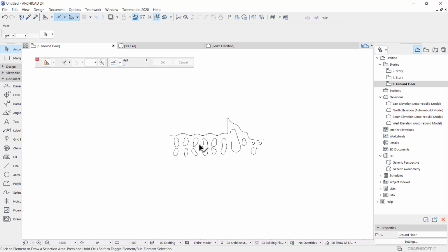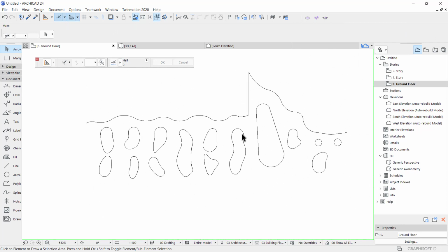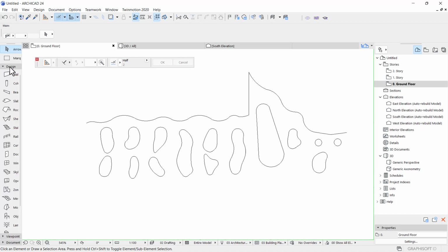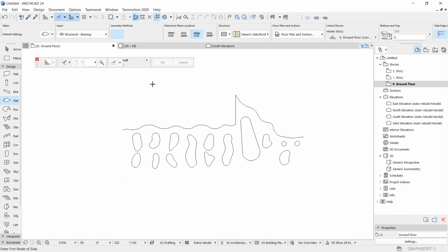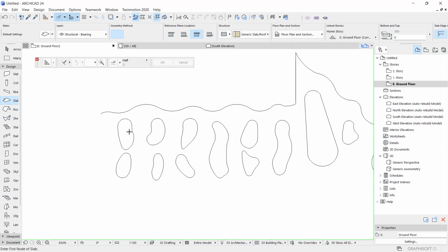So we want to fill this with slabs because these are going to be our main things, slabs. So you click on slab. This is the part where you learn how to make perforations. If you've drawn any shape of perforation, say you have a certain design of perforations that you want, once you do the geometry for them, like you draw the lines on how you want to do them, you come to the slab tool and you hold spacebar. Then you just want to fill all this with slabs.